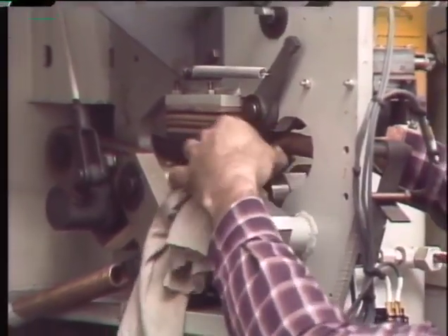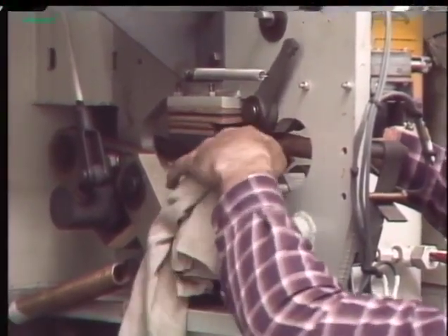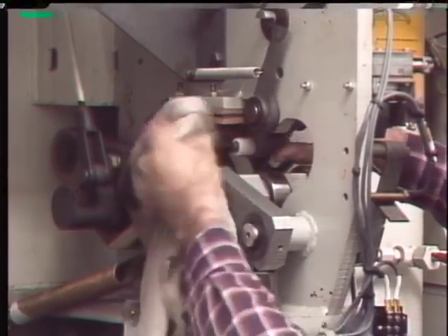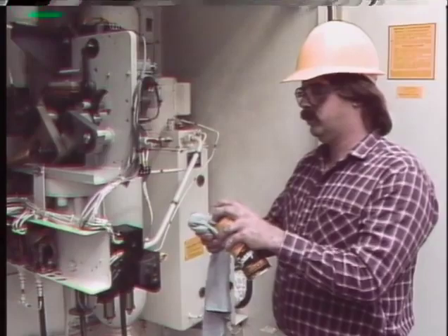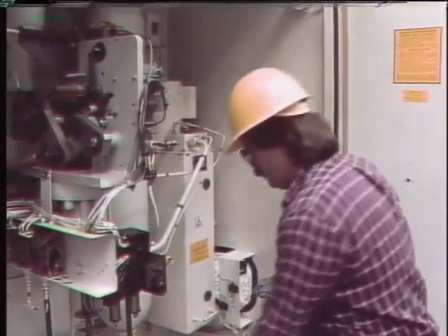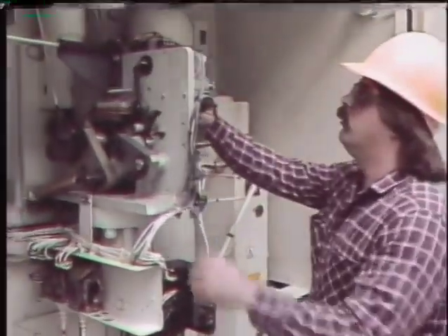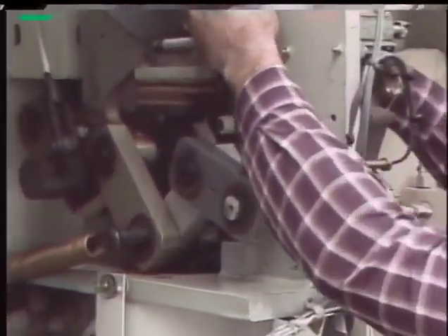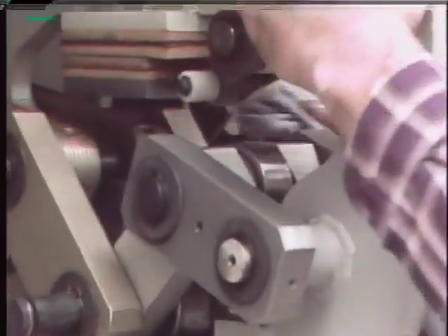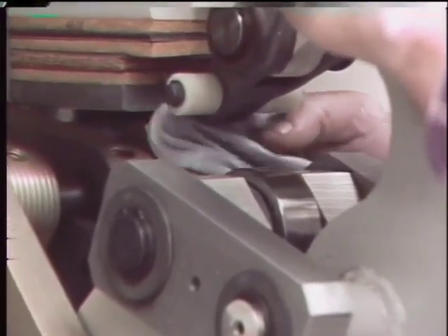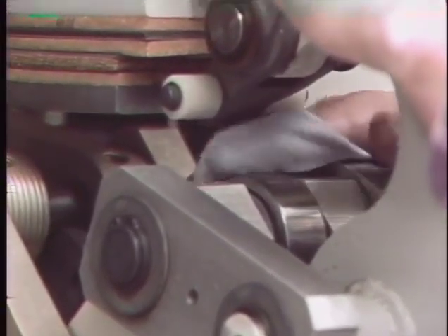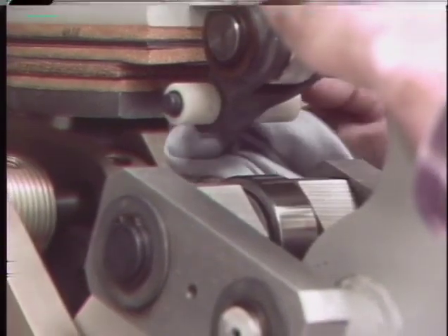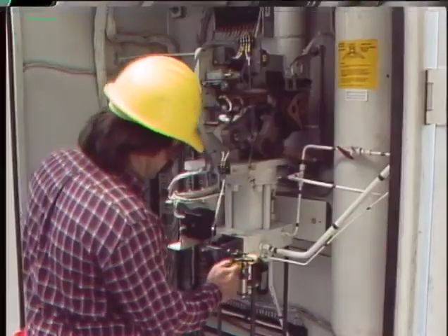So it's a good practice to wipe off the links, levers, control coils, latches, rollers, and other mechanism parts. Dirt or rust can be cleaned with a solvent if necessary, and a small amount of rust inhibitor can be applied. While cleaning the mechanisms, you can also inspect them. Signs of wearing may indicate that some lubrication is needed. Parts with excessive wear should be noted for possible replacement.